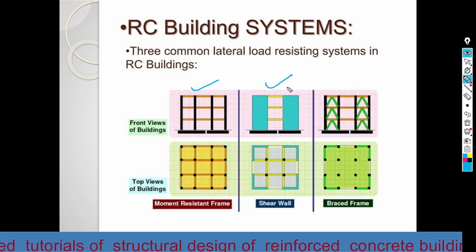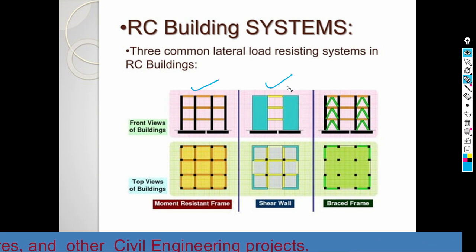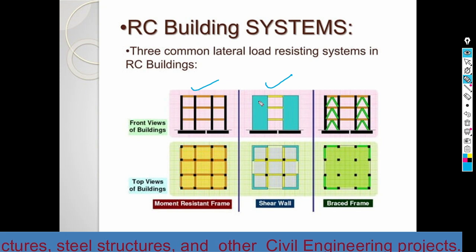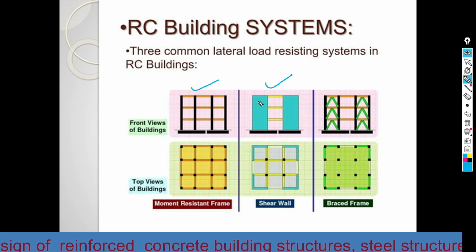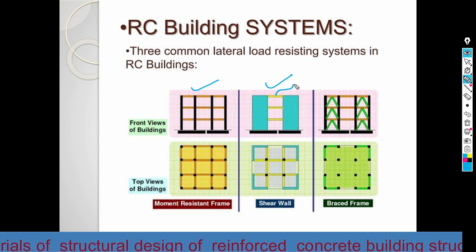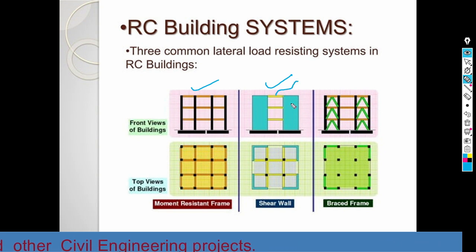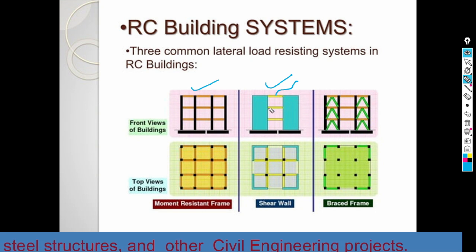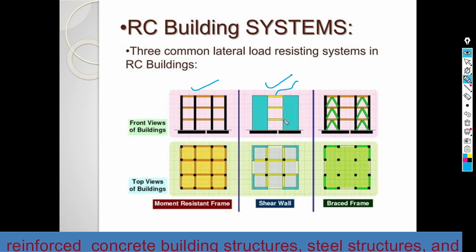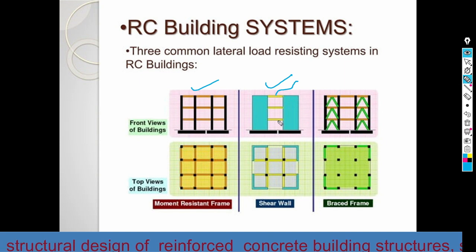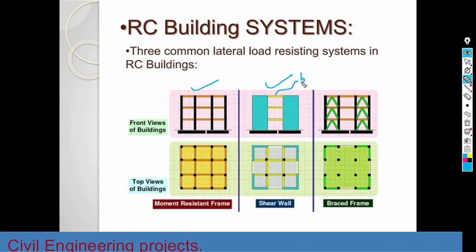And this one is the shear wall at the right and left sides, with a coupling beam which connects the shear walls at intermediate locations or at each level of the story. And this one is the beam.